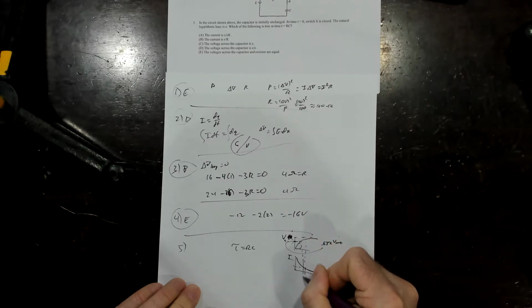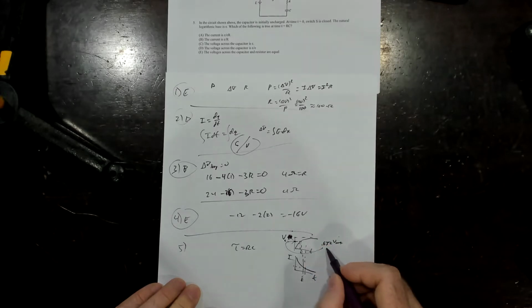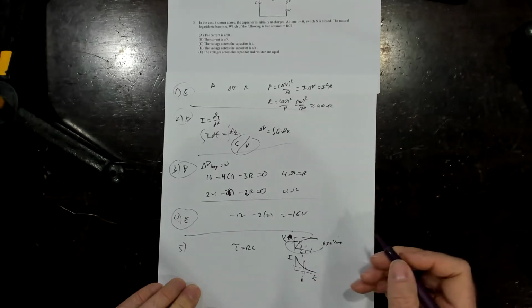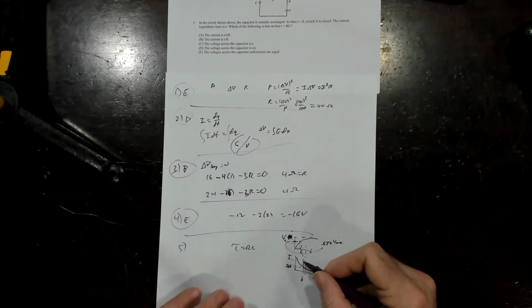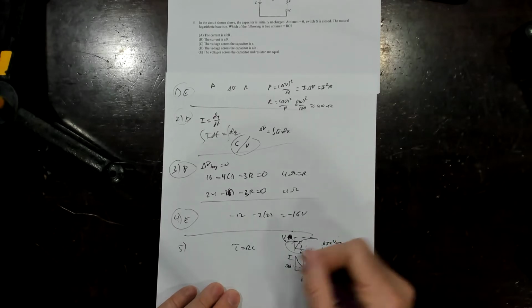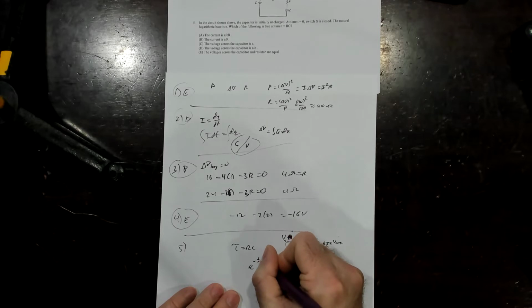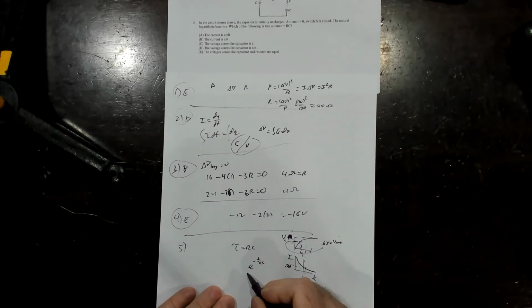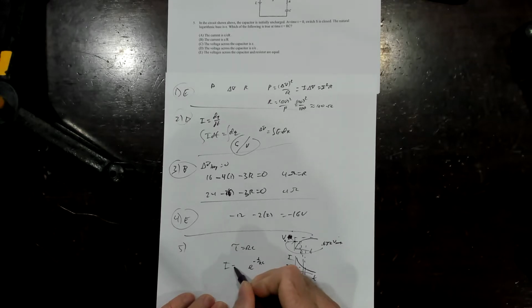These didn't line up, but you get the idea. At that same time constant, what's 1 minus 0.63? I'll be at 0.368 of the maximum I. Because what's this going to be? You might remember the exponential looks like e to the minus t over RC, depending on which one we're looking at. If I'm looking at this one, my I is my I max times e to the negative t over RC.